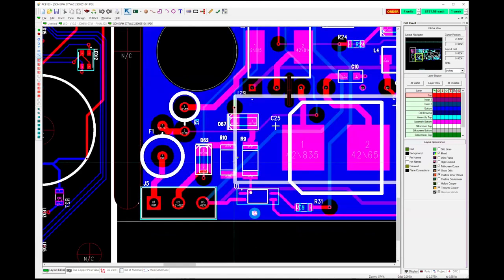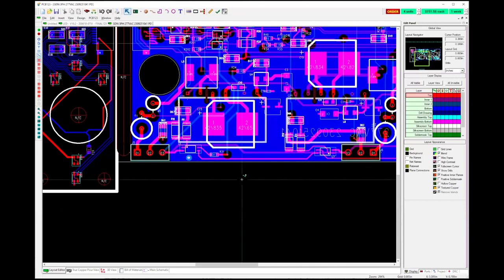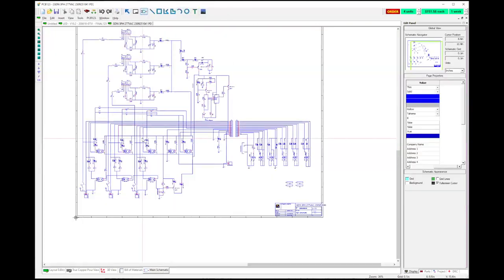You'll have guide wires on all of your parts to tie them all together, but when they're spread out randomly from before you place your parts, it'll be pretty hard to follow. And it's kind of a dynamic thing. If you move a part to another location, if it's connected to more than one place, that connection might change to that other part. So you can't really just say, oh, the guide wires go from here to here, so I'll just hook them up by that. It's better to use your schematic to drive the placement of the board.